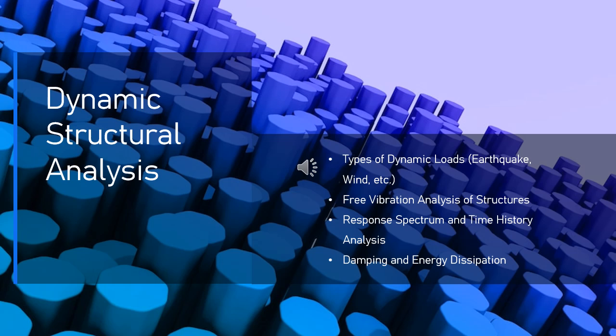Computationally intensive. It requires solving differential equations at many time steps, which can be computationally expensive, particularly for large structures or long-duration events. Requires detailed input data. It requires accurate time history data, e.g., ground motion records, or detailed load history data, which may not always be available. Complexity. Due to the need for time-dependent load data and numerical methods, it is more complex to set up and interpret compared to response spectrum analysis.